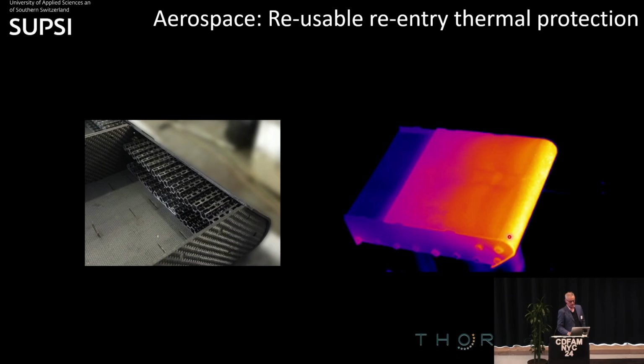And we were making a sandwich structure, like you see here, in which the inside was filled with the ceramic material. The goal of using this was twofold. On one side, you have a sandwich structure which keeps integrity. On the other side, we were flowing a gas inside here, and we were removing heat from the leading edge, which you see here is the most heated part of it.